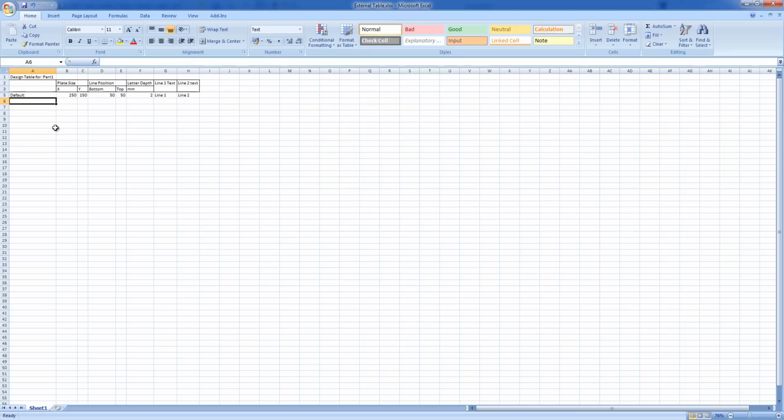So let's create a new order. And we're going to have a same width plate, but we're going to make it taller. I'm then going to move the bottom row up a touch, but we'll keep the top row where it is. Same cut depth. And let's give it some values. So, typing those into the two cells. You will notice it gives you a tooltip of what the property is, but you can ignore that if you don't understand it. That's absolutely fine.